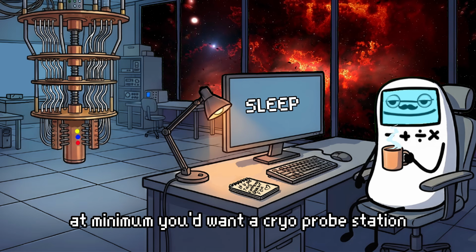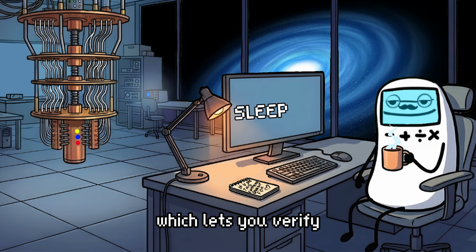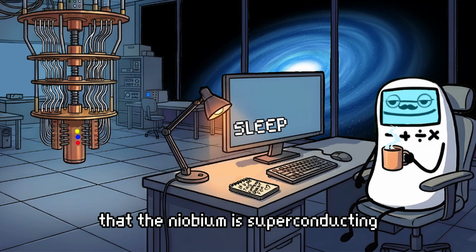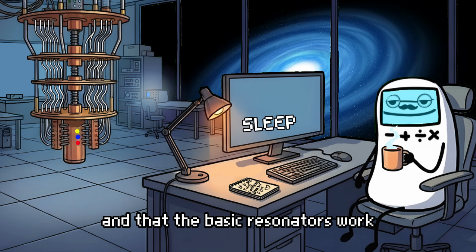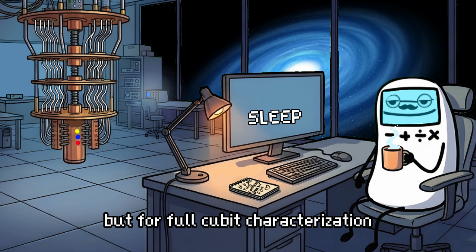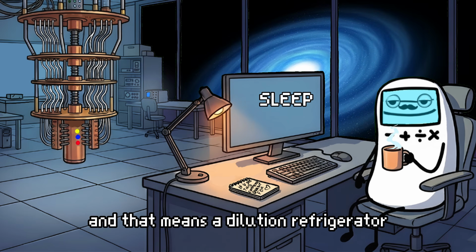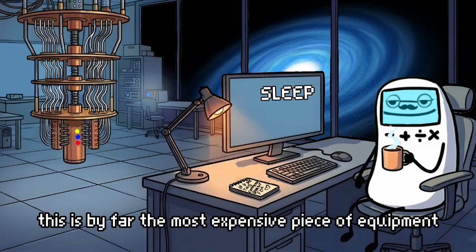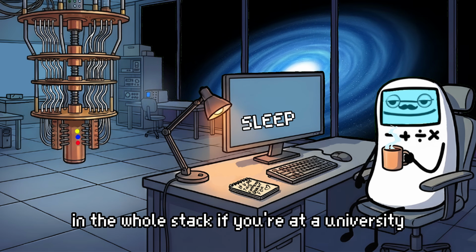At minimum, you'd want a cryoprobe station that can cool a chip to 4 Kelvin in liquid helium, which lets you verify that the niobium is superconducting and that the basic resonators work. But for full qubit characterization, you need to go colder, and that means a dilution refrigerator. This is by far the most expensive piece of equipment in the whole stack.